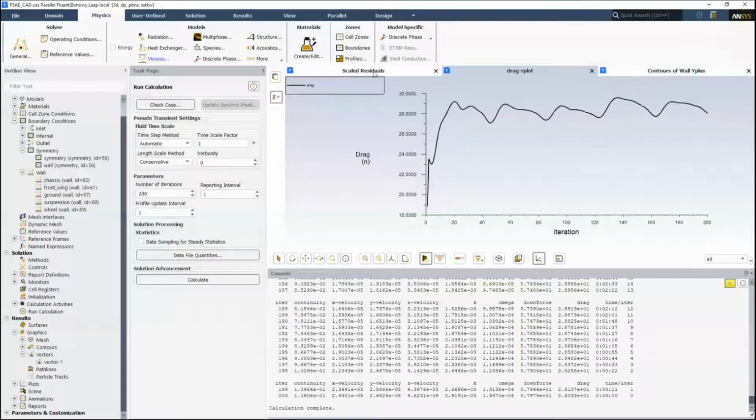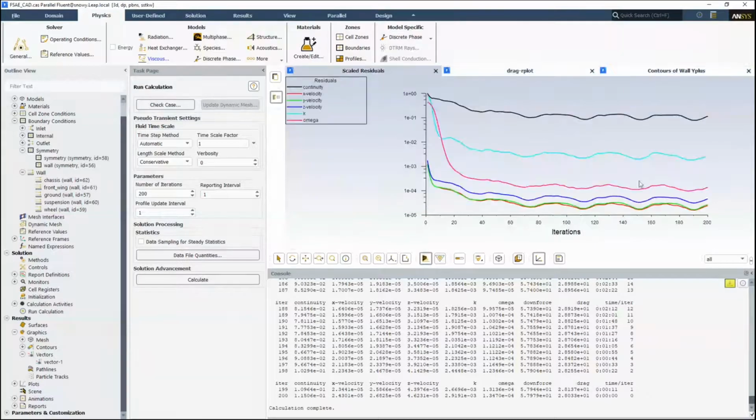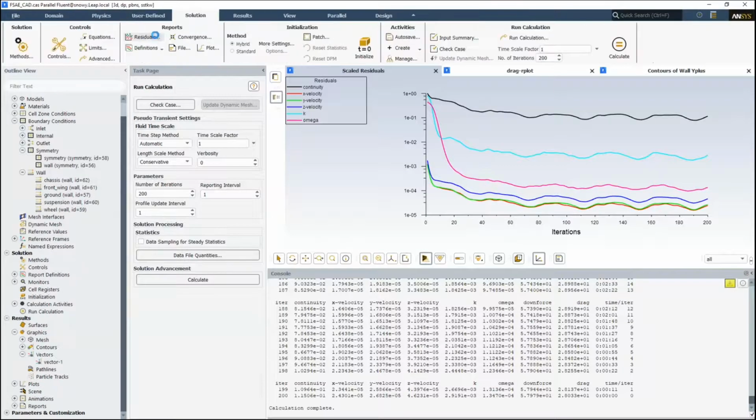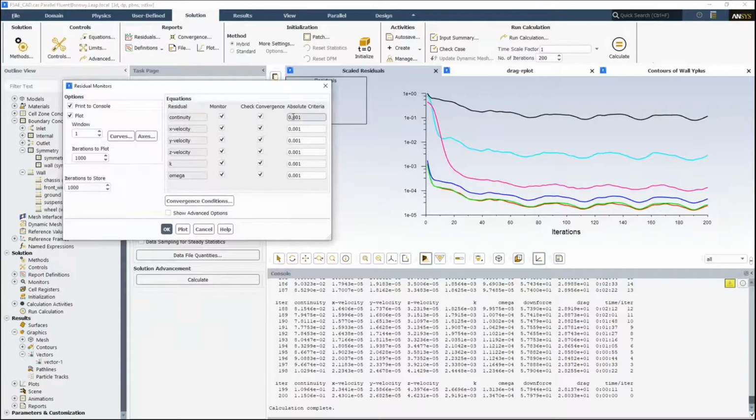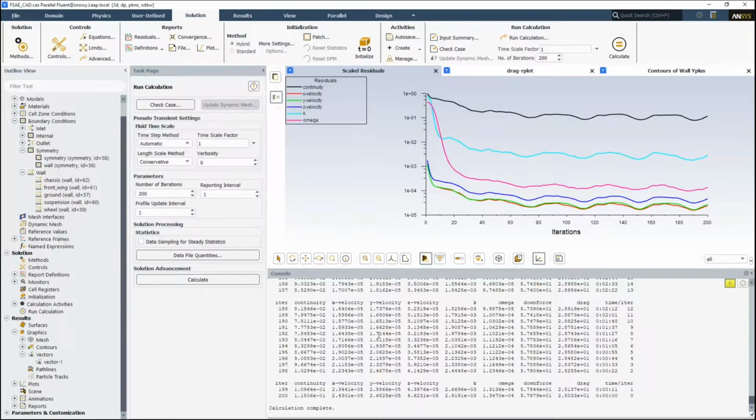So we've lost our lift plot because I was playing around putting extra contours on. But we have solved now. You can see we've solved for 200 iterations. It's gone all the way. It hasn't converged, because we haven't reached the 1e to the -3, which was the criteria. If we go back and remember that, we look at these residuals, our convergence criteria is 1e to the -3 for all. Okay. So we haven't actually converged in terms of when we're using our residuals to ascertain convergence. Remember, residuals are the difference between the left-hand and the right-hand side of the equation of our Navier-Stokes equations.